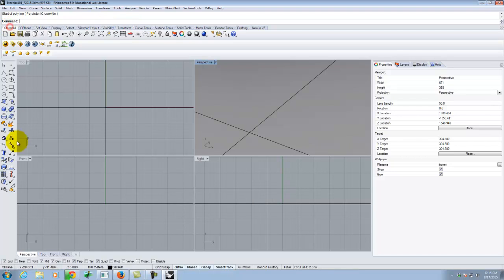The other thing is we have a bar that runs down the side here. This toolbar has the most common tools in it. So it has polyline, for example. It has the select tool. We have basic primitive shapes. You'll notice that on a lot of these there are also little triangles at the bottoms. Those triangles mean that if I click and hold, I'll get a bigger menu with more shapes or more tools to pick from.